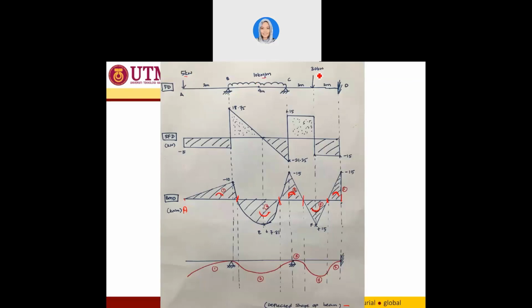And be very careful at the support, there is no deflection, so you have a little bit of straight line here before it ends.